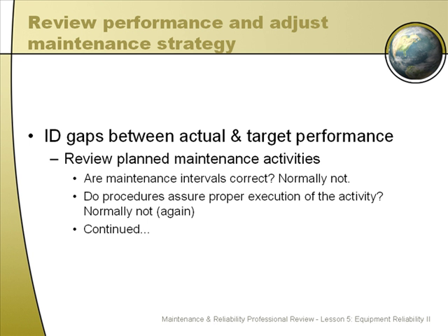Procedures need to be very clearly developed for the equipment in its specific application. The instructions from the manufacturer are only a starting point. Things that you've learned at your facility are added into those procedures, and techniques for doing the work on that particular piece of equipment are sometimes different than the manufacturer recommends. You need to take this into account. Your procedures need to be instructions that would allow the least skilled maintenance technician on your team to do the job perfectly every time.